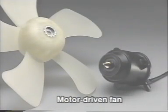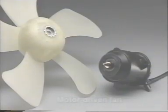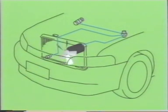The motor-driven fan is activated only when the coolant temperature is high. Most front-engine, front-wheel drive vehicles use this type of fan. Since the fan speed does not change with the engine speed, this fan provides high cooling performance when the vehicle is driven at low speed.